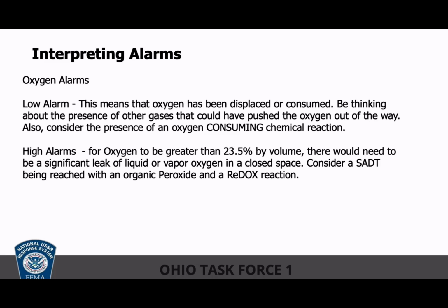If you were in an open area and you had higher than 23.5%, you're in a huge problem, because if we've created that much oxygen in an open area, even in a room, you've got big issues. But if we look at closed atmospheres, containers, pipes, vessels that get above 23.5%, that's also really concerning, but you're at least in front of the problem.